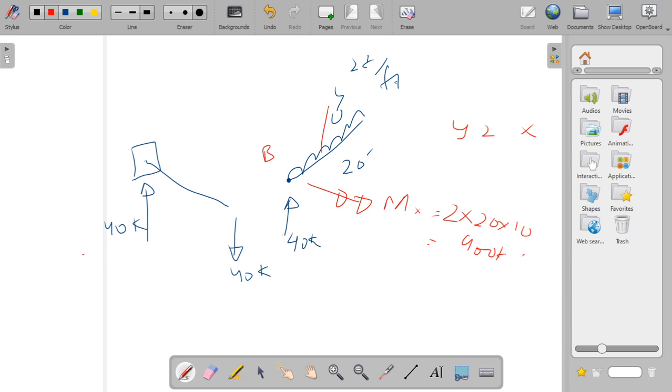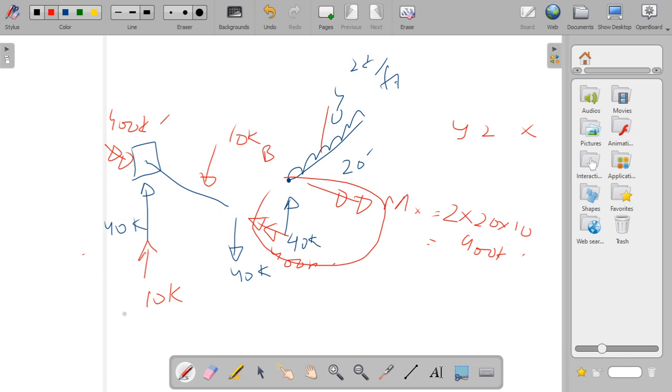And this joint has to be balanced, so I have balanced this here. Again 400 kip foot, and again this would be balanced here. Every joint has to be balanced, like this joint has been balanced. Every member has to be balanced. Again, I have 10 kip here as well, upwards. So this should be balanced here with 10 kip. So 40 plus 10 gives us 50 kip. So here the load would be 50 kips.